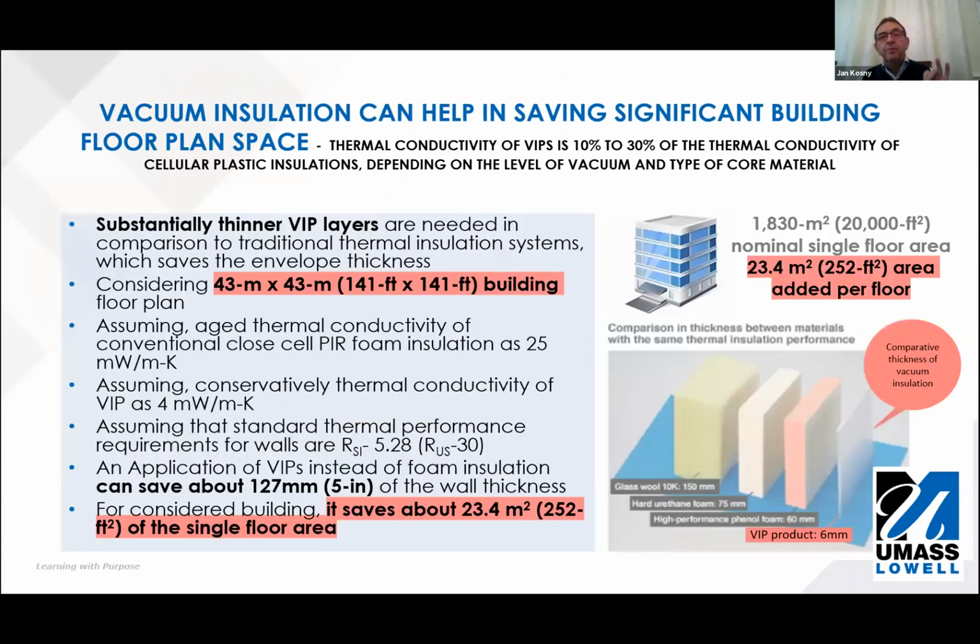I would like to stop here on the cost analysis, because for years we tried to justify using vacuum panels using energy calculation. It is a very good attempt, but not very successful. The major value coming from using vacuum panels is space.